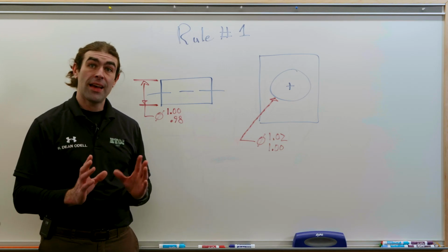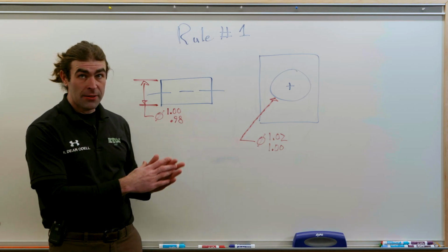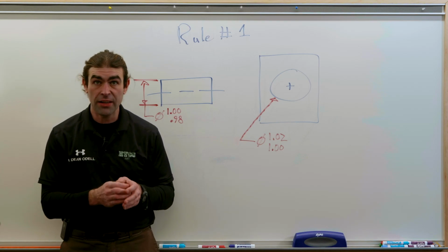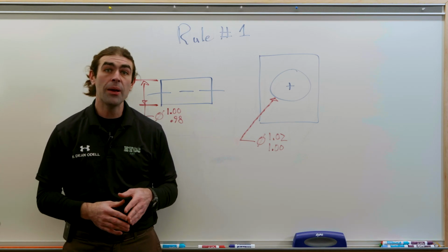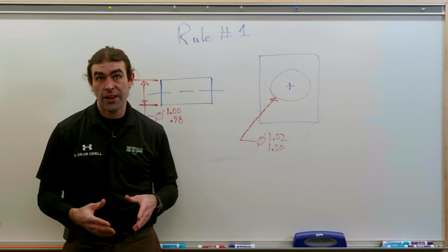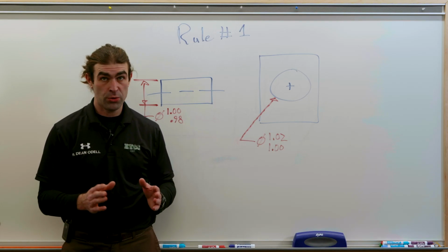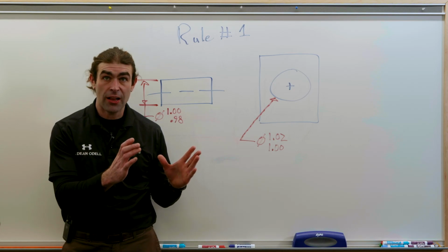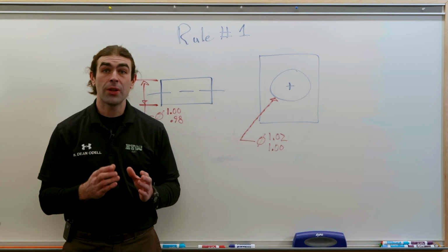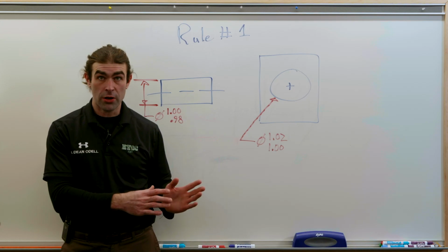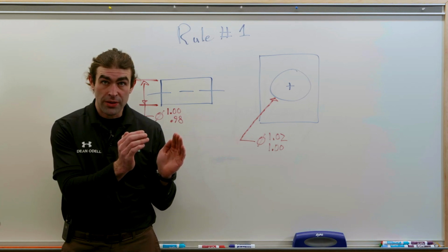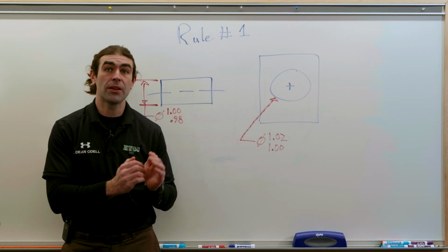So when you make that gauge to check this pin, the gauge has its own tolerance, which is usually really, really tight, tenths of thousandths of inches. The gauge maker, the designer, has to decide one of two things. Either the gauge is going to have the tolerance on the inside so that it may reject some good parts, right? So the hole is set to 1 inch, but the tolerance says the hole can be a little smaller.